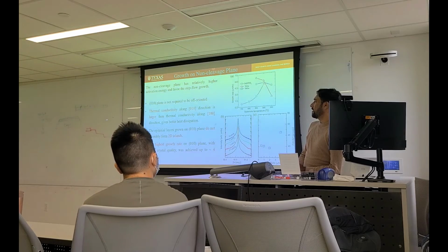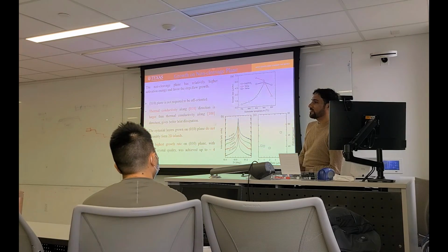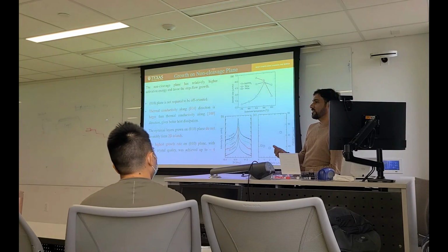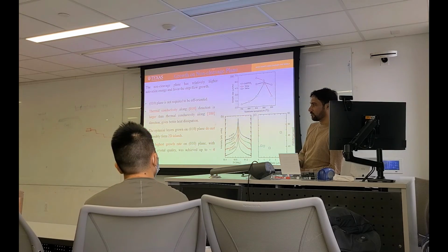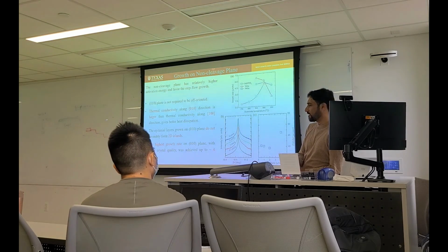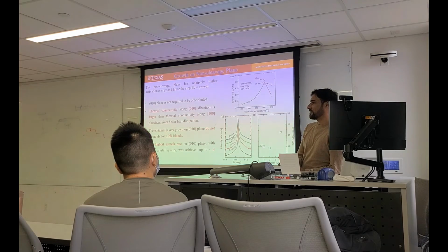Non-cleavage plane: the synthesis is difficult. Several substrates break, sometimes they need polishing also. But growth is really good on the non-cleavage plane. Every time you will get step flow growth. Yeah, so this is the difference.